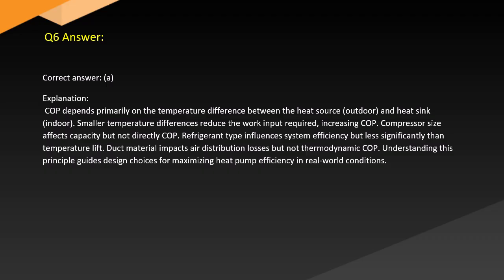Answer. Correct answer: A. Explanation. COP depends primarily on the temperature difference between the heat source outdoor and heat sink indoor. Smaller temperature differences reduce the work input required, increasing COP.